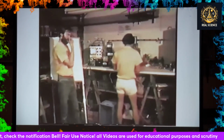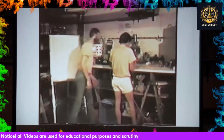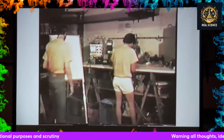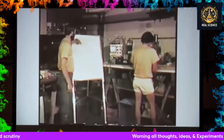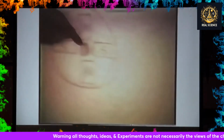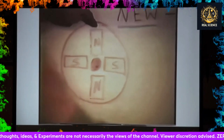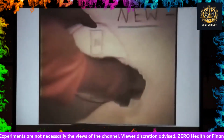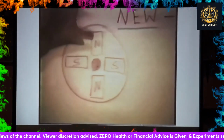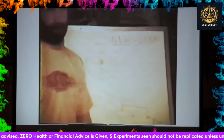As Michael is changing the location of the brush here, I'd just like to say that basically what we're doing, for the first test you just saw, we had one brush on the shaft here, and another brush riding on the disc out at this location, so that as the different pole faces move past between these two brushes, they produce EMFs in opposite directions, as would be expected.